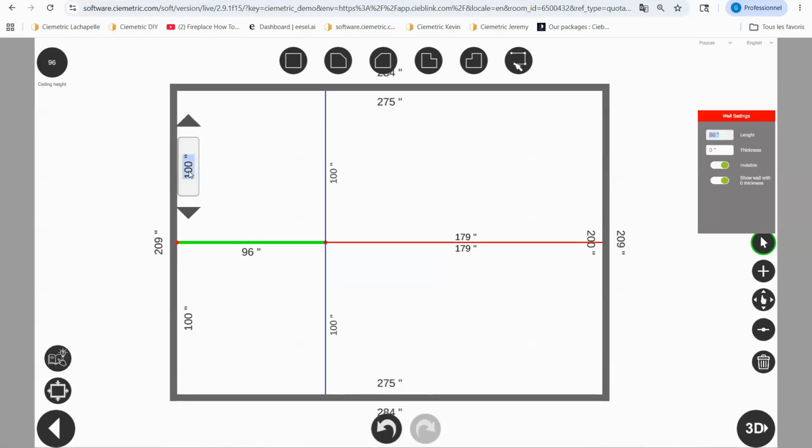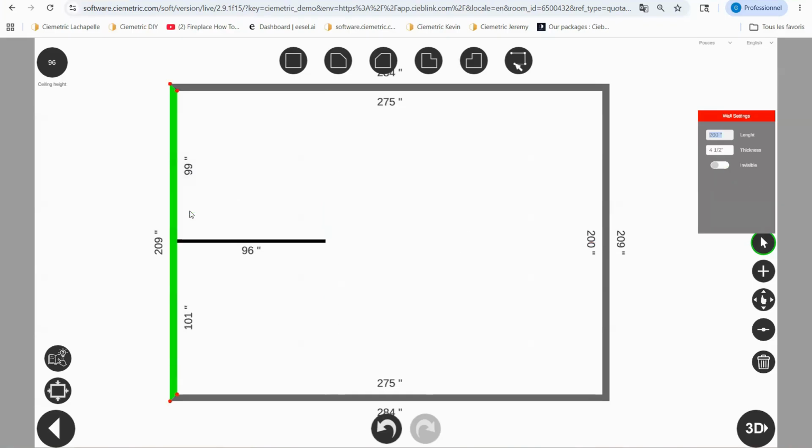You can reposition the wall by typing the value that you want. In this example, we have 25.5 for the countertop at the top, we want to keep a space of 48, and 25.5 again for the other countertop. So it's going to be 48 plus 51. I'm just going to calculate it. 48 plus 51, it's 99. When you type 99 and select the arrow at the bottom, it just repositions the wall, keeping the size of the room.